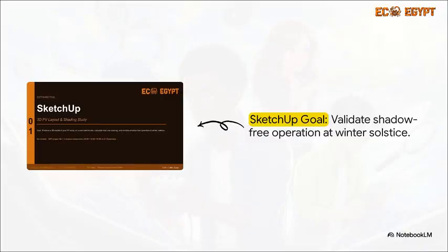Now, your specific goal in SketchUp is to produce a 3D model of your PV array sitting right on a real satellite site image. But it's not just to make it look pretty, right? You have to calculate the exact inner row spacing and validate shadow-free operation at the winter solstice. By capturing shadow screenshots at 9 a.m., 12 p.m., and 3 p.m. on December 21st, you prove your layout actually works when the sun is at its absolute lowest point.